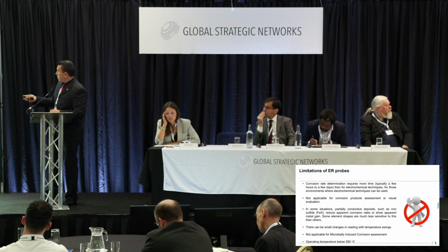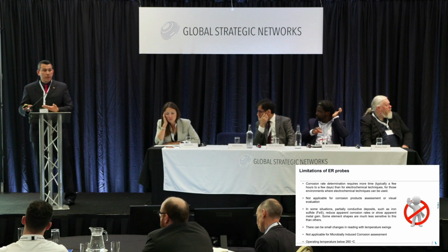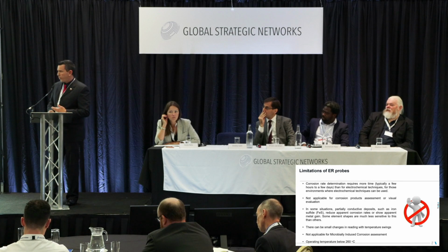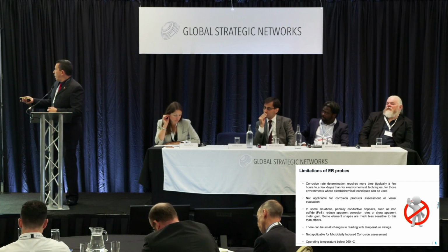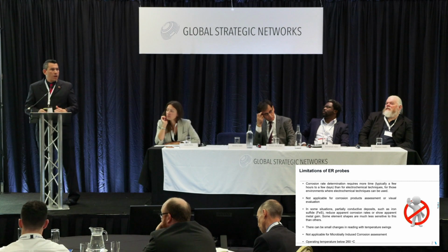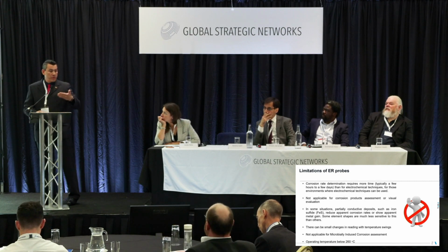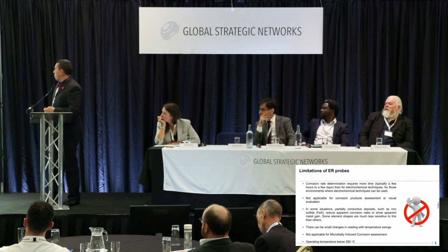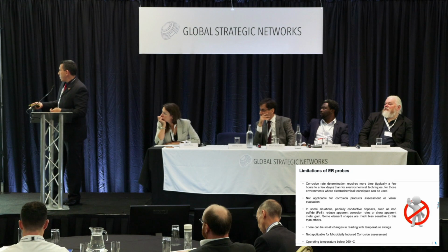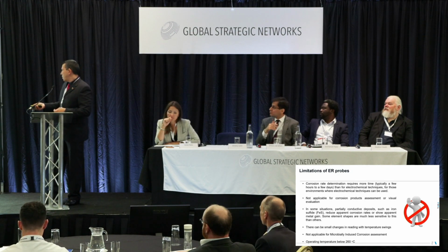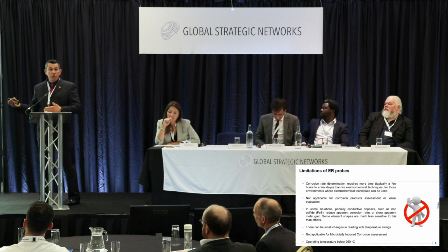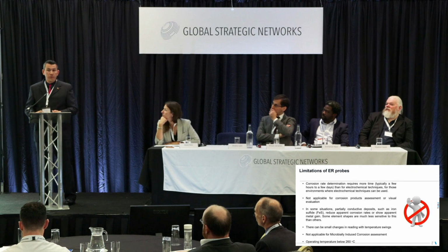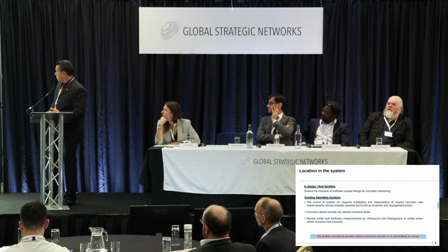Yeah, in some cases, corrosion rate, depending on the selection of the corrosion probes, can take a lot of hours or days to have a reading. And you can't have any information about degradation mechanisms from the visual inspection. Big difference compared to corrosion coupons. I already explained this one. Also temperature. In some processes, you might be interested in using them at temperatures above 260 degrees. It's not possible these days.